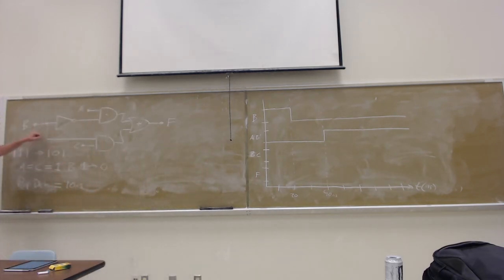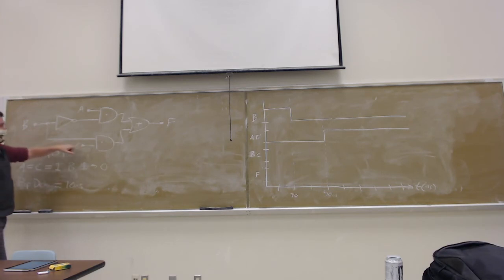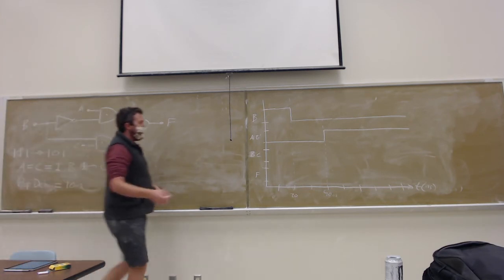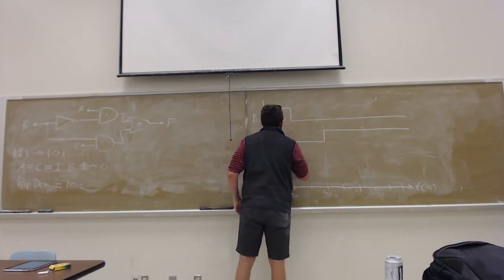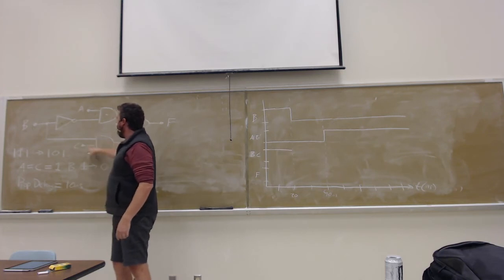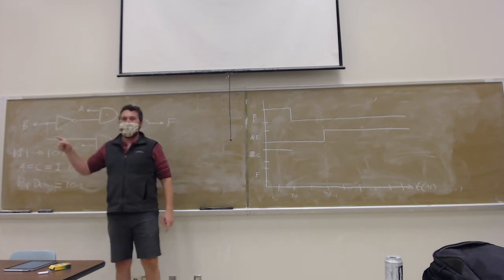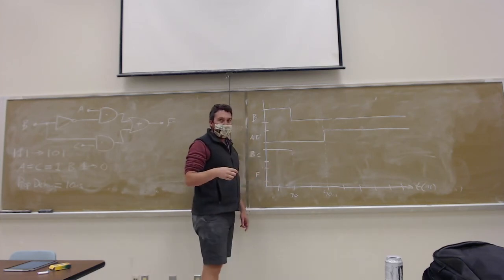Next up, let's look at B and C. Now C is equal to 1, that's an AND gate. So it starts off its life where? With 1 and 1, right? So the AND gate BC starts at 1, and then when B transitions to 0, it's going to go to 0 because it's going to have 0 and 1. But its transition will occur at 30 nanoseconds, right?